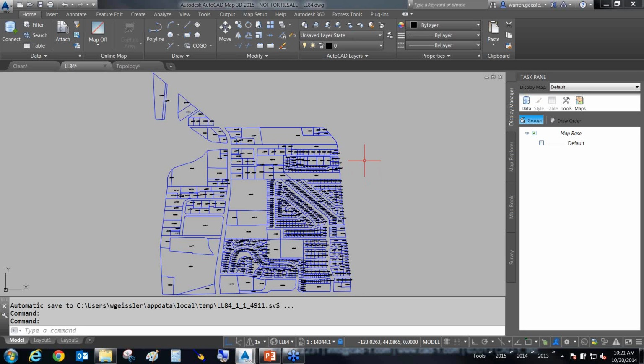Okay, so let's say I've got lat long. I've got either, like I said, GIS information or AutoCAD information, but I need to get this in. Let me tell you, when working with different coordinate systems, I see this happen a lot. You cannot just pick up the drawing, move it, rotate it, and scale it into place. It won't fit. It doesn't work.